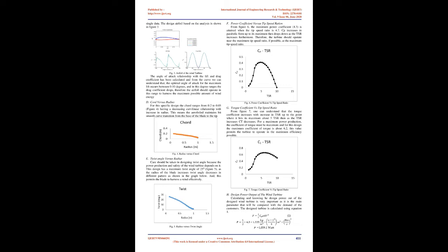Structural performance. The stiffness plot depicts the stiffness along the first, EI1, and second, EI2, principal axes and depends strongly on the shell thickness. The stiffness in the edgewise direction will always be larger than in the flapwise direction. This is shown in Figure 2, where EI2 is much larger than EI1. The bending moments along the first, M1, and second, M2, principal axes, the flapwise, UN, and edgewise, UT, deflections, and the deflection shape of the first flapwise eigenmode, UI, FLAP1 and US, FLAP1, are included in the structural plot.